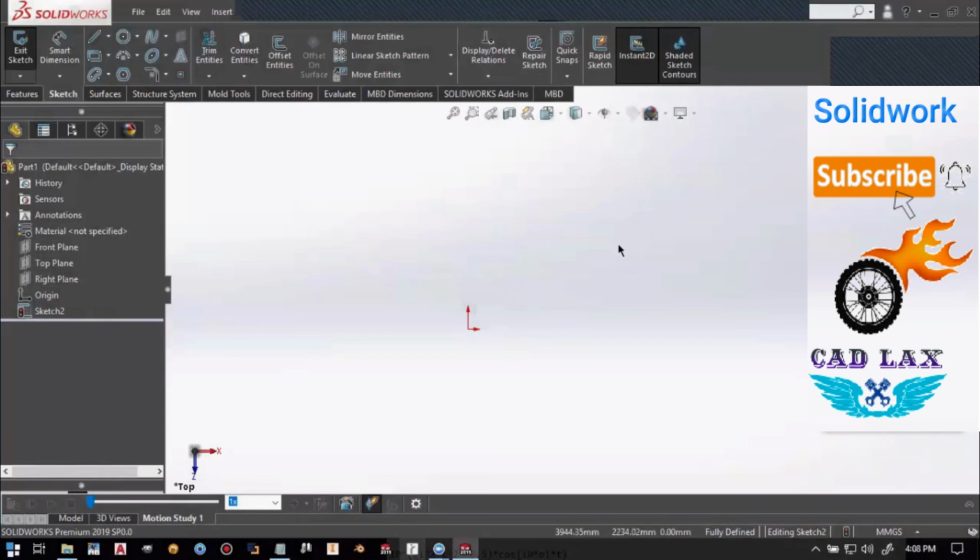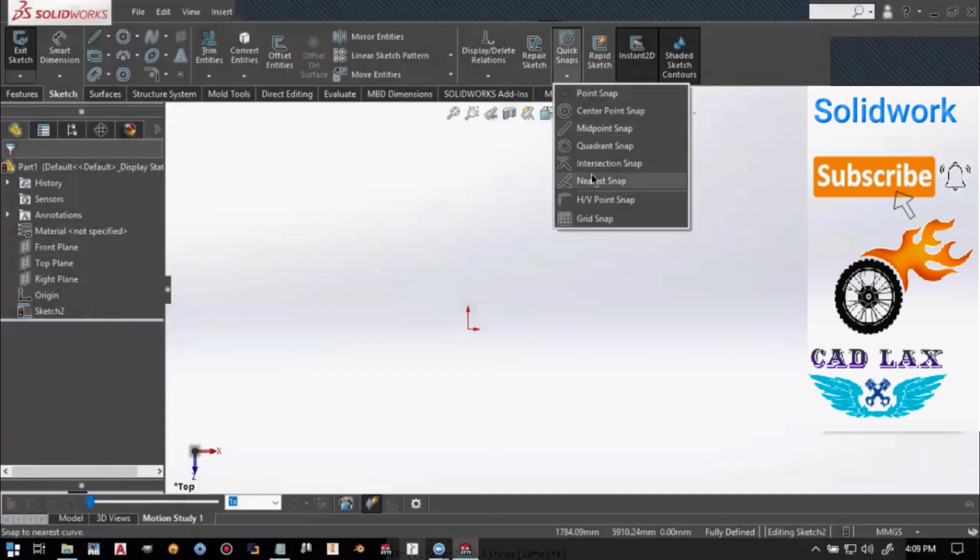Repair sketch. Whenever we find a sketch, like you can see if there is any gap between the points, the sketch is not closed and you can't extrude it directly. So this tool is pretty useful to find the gap between the points. Quick snap. As you can see, the points between the geometries automatically get snapped, so you can modify these snap points. This is similar to AutoCAD.